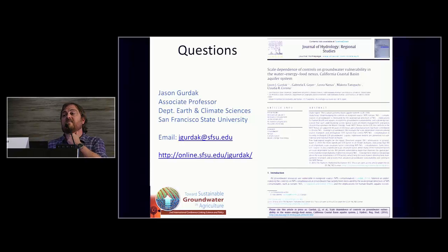Sure. There's all kinds of considerations when you're measuring for DO. One of the big ones, if you're sampling a domestic well, oftentimes the water supply is after the pressure tank. So the water's been sitting in the line, and that DO value is not indicative of the aquifer at all. If you're doing a groundwater quality sample and the tube to your submersible well is exposed to the atmosphere and it heats up, you can be degassing the water sample. A lot of this data came from the USGS, so they take great care in making sure their DO and other water quality parameters are indicative of the aquifer.